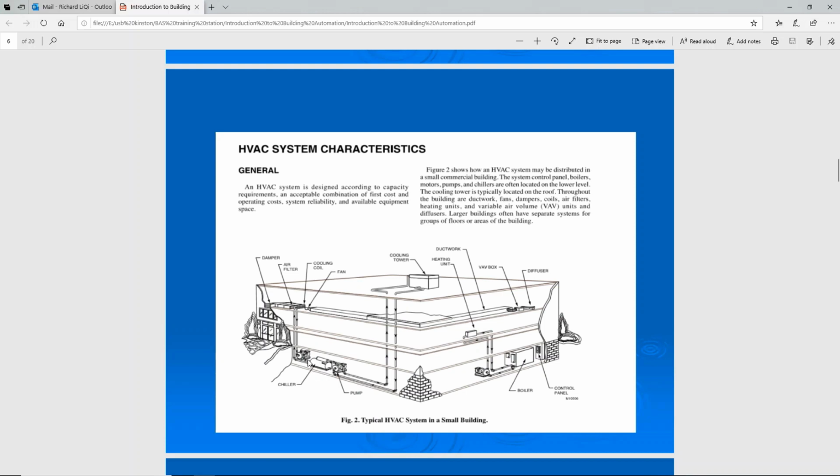A chiller provides the cooling energy to serve the building, and there is zone equipment such as an air handling unit to serve the big area, and then a small unit like a VAV box to serve a small area like an office. There are heating units to support small areas or window-side heating loss, radiators, and exhaust fans, makeup units, and dampers.